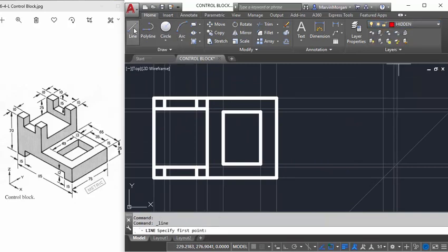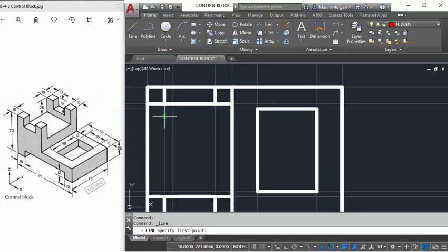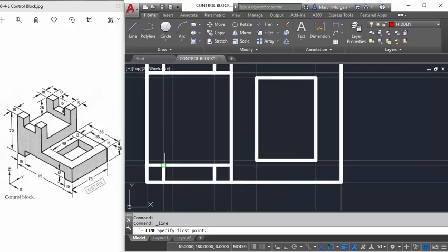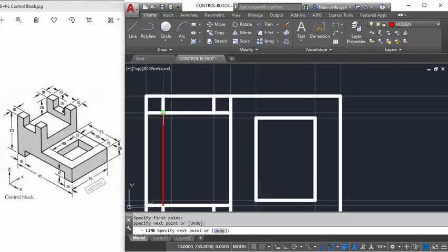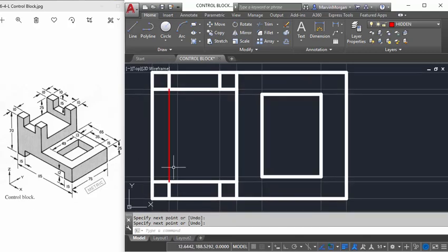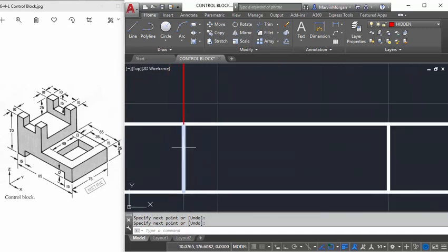So from the top view, we cannot see parts of this cutout down here. We cannot see this underside surface of my arrow, and I can't see the underside surface here. So to identify that, we're going to put lines that go here all the way across to here. The reason why I started at this location to this location is because there is a drafting rule that says that object lines override hidden lines. So if there's a situation where a hidden line needs to go across, the object line wins, mainly because it's thicker than the hidden line.